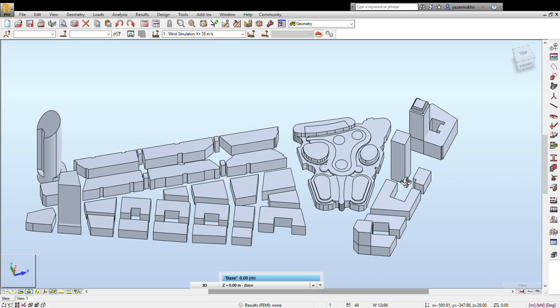The specific building that needs to be studied, for instance this one, will be filled on the physical model with a lot of sensors all around the facade to make sure that the loads generated from the wind are recorded. These values are then given to the structural engineers and facade consultants, to be able to carefully design the facades or the cladding systems, whether it is stone or metal, according to the resulting loads.